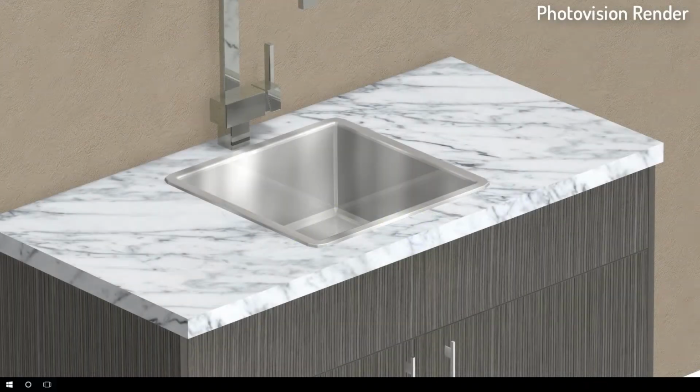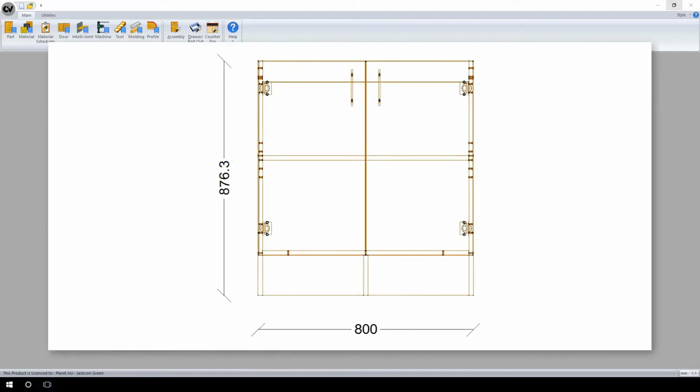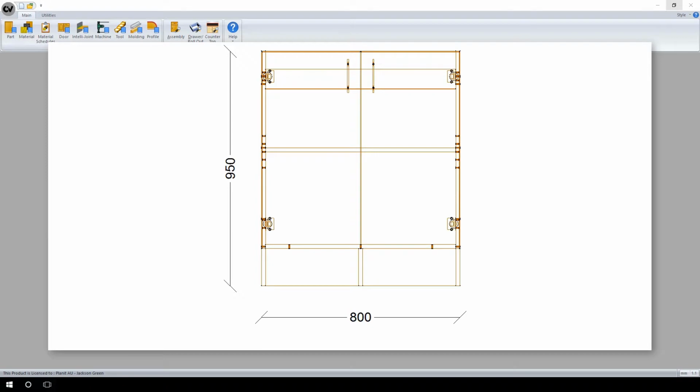Many users wish to achieve this when creating a sink cabinet, with the rotated rail making way for such things as plumbing or sink hardware. If we were to simply rotate an existing rail inside a job, it would look like this. This correctly achieves our result. However, if the cabinet is resized, the rotated rail does not correctly adjust with the cabinet.